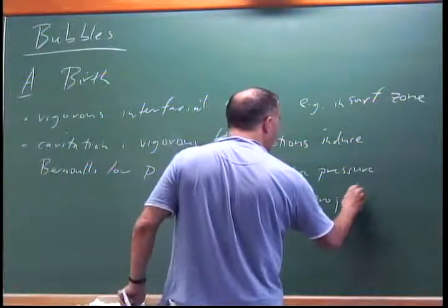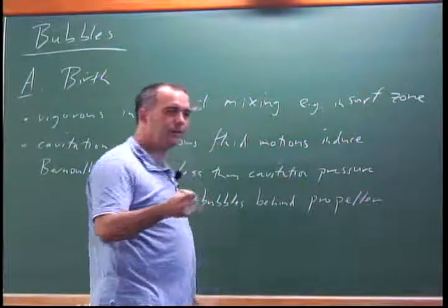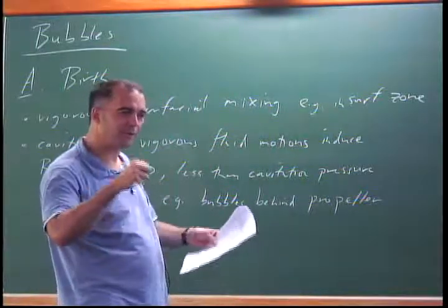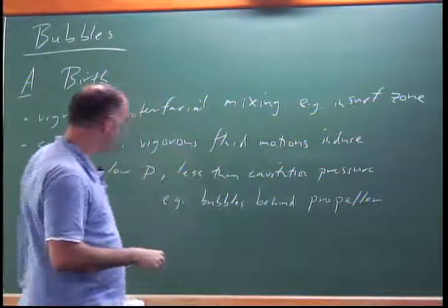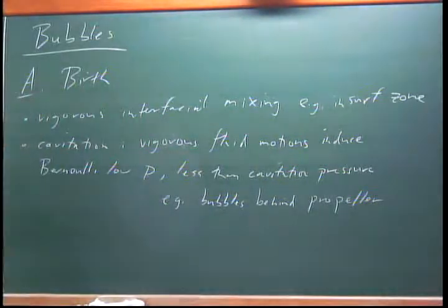And you see, by the way, these bubbles, when they explode, they always scour. They damage the propeller because when a bubble explodes near a wall, there's a spike, and you get pock marks all over the propellers.